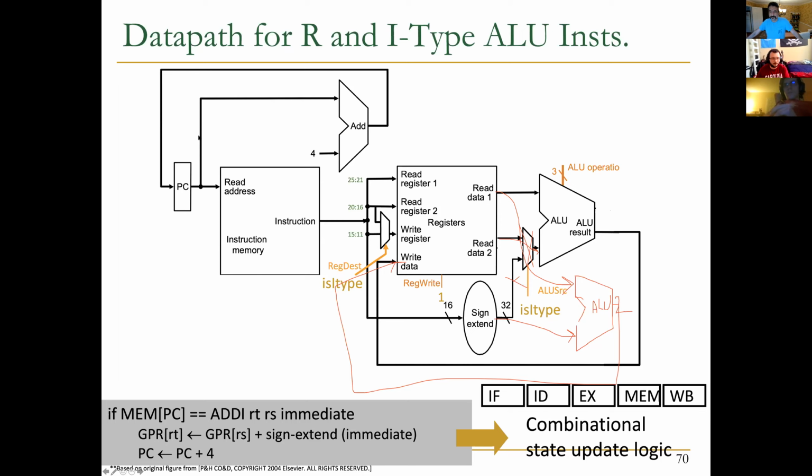I just thought of one more thing to add to what I said, based on just the sizing constraints, it seems like an ALU would take up a lot more space on a small board than a couple of multiplexers. So implementing another ALU as opposed to two small multiplexers seems like a waste of space on a board. You can minimize the space you use.